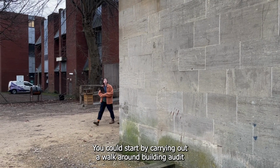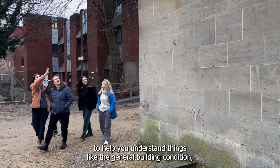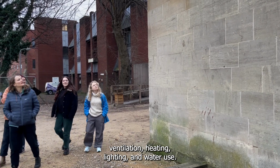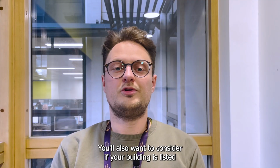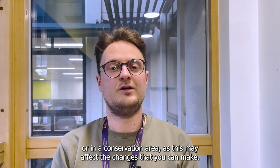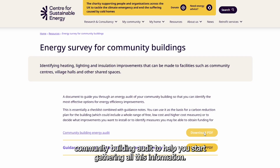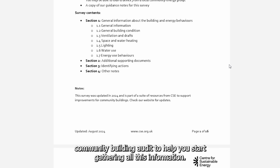You could start by carrying out a walk-around building audit to help you understand things like the general building condition, ventilation, heating, lighting, and water use. You'll also want to consider if your building is listed or in a conservation area, as this may affect the changes that you can make. You can use CSE's Community Building Audit to help you start gathering all this information.